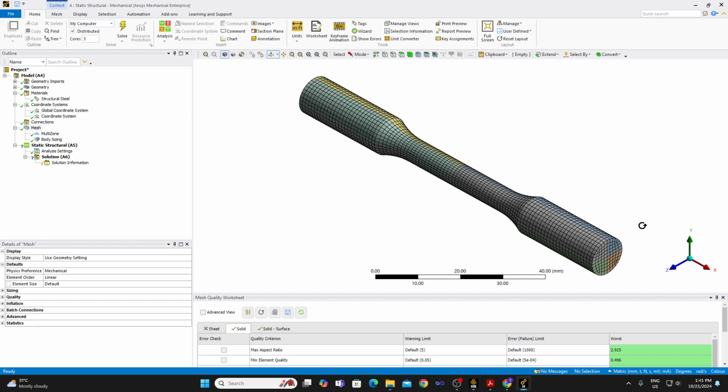We can also work with this one, but if you look at this carefully, this is a dog bone specimen, right? It looks like a bone where the two ends are wider and the middle portion is thinner, and that is actually the tensile region. While undergoing the tensile process, that is the region that will undergo elastoplastic deformation, and the wider portion will have only elastic deformation.